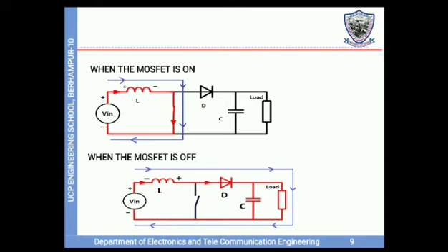When the MOSFET is on, current passes through the inductor, through the MOSFET and finally to the ground. As mentioned earlier, the inductor does not allow sudden changes in the current, meaning when the MOSFET is on, the inductor won't allow full current from the input to pass through the MOSFET and to the ground. Instead, the current will rise slowly in a microsecond time frame.